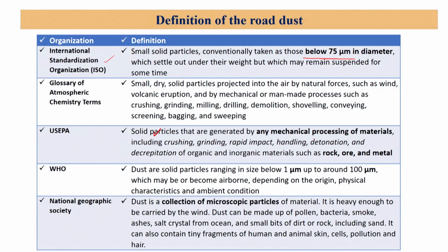You have heard me in the last lecture say that aerosol size is typically 1 to 100 micron. Okay, so this dust is large enough that it will be deposited back, that is true, and most of the road dust, these bigger particles, is resuspended in the atmosphere during vehicle movement. Mind you, it is also very important that when vehicles are plying on the roads, these particles get attached to other particles, or they are broken down into smaller pieces, and they can become small enough to be suspended in the atmosphere for a longer time. So this is very important.